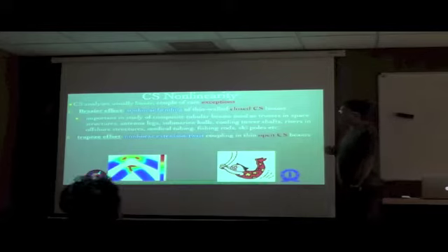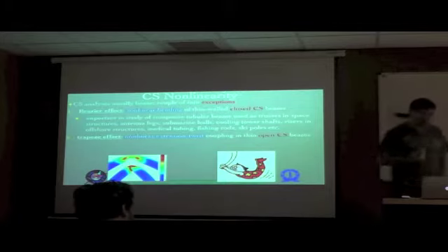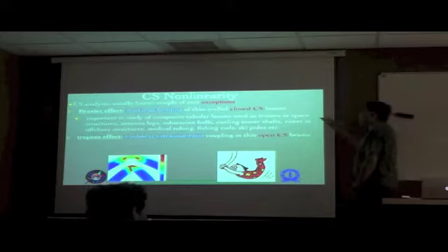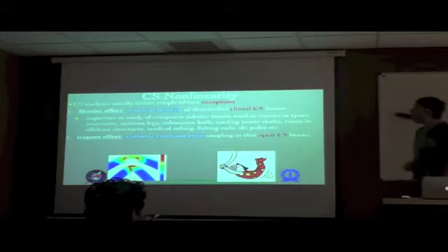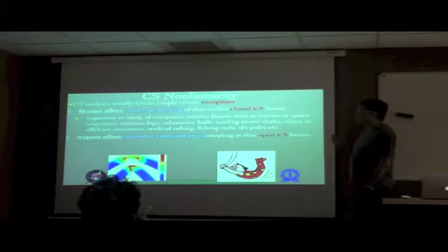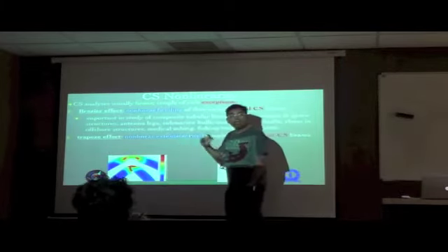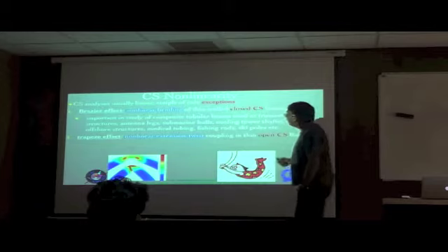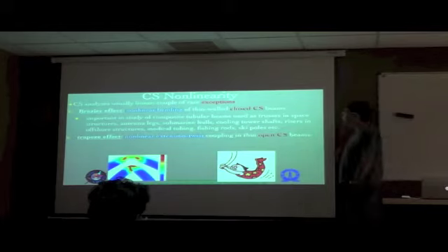Now, why these are important is that these kinds of beams are very commonly used in engineering. Of course, we know a lot of aerospace applications of it, but there are non-aerospace applications as well. Again, in space, you see that they are used, for example, in trusses and many space structures where you have these closed cross-section beams, typically circular, sometimes elliptic, depending on the particular loading ratios. And then in antenna legs or radar legs, for example, then in submarine hulls, cooling towers, especially in power plants, the shafts which are used there, they are typically of closed cross-section, which are thin-walled.